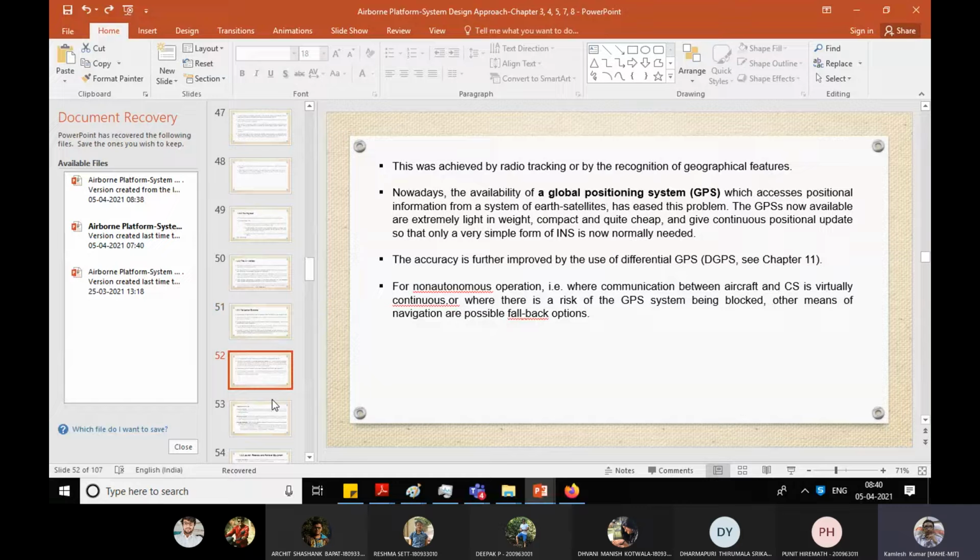Normally you have seen that under GNSS, lots of receivers are there, and receivers are very cheap. So that is integrated with the aircraft. Most aircraft today have this type of system, and from the GPS receiver they are accessing all the details in the geodetic system: latitude, longitude, and altitude. And this can give you positions in X, Y, Z. If you talk about the Cartesian coordinate frame, then you have position information as X, Y, and Z.